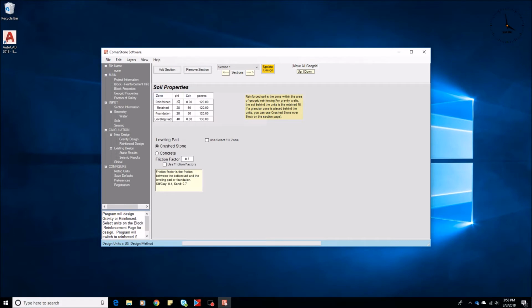We're going to be in 34 to 36 degree soil. I usually default to 28 on a standard design, a silty sand soil, conservative design. But it's a choice of the geotech, it's a choice of material that's out there.